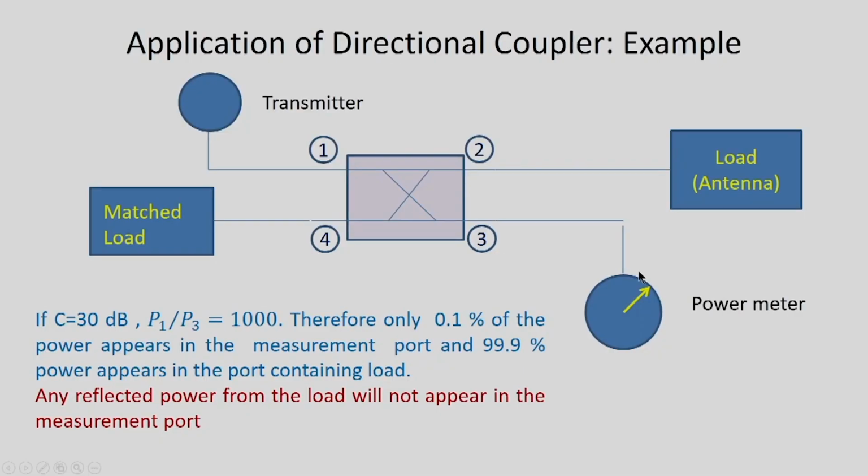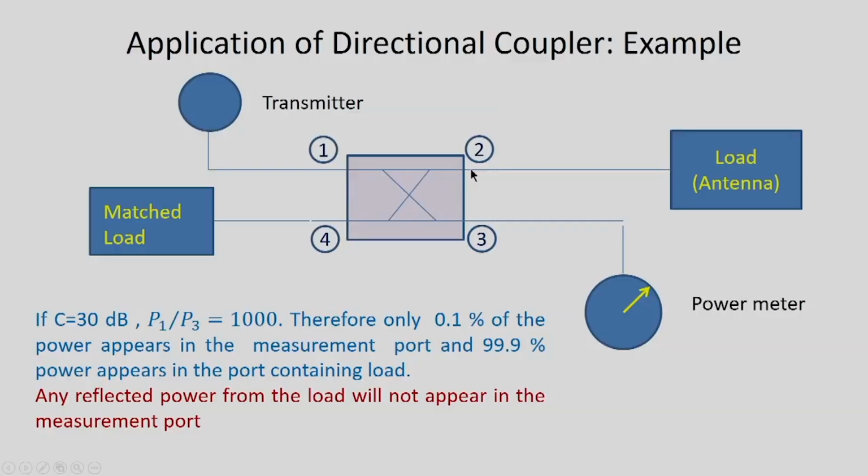It should be noted that because of some load mismatch, if any power is reflected from the load, then it will appear at port 2. Now, port 2 and 3, they are isolated. Therefore, this reflected power will not appear in the measurement port and will not affect the measurement.